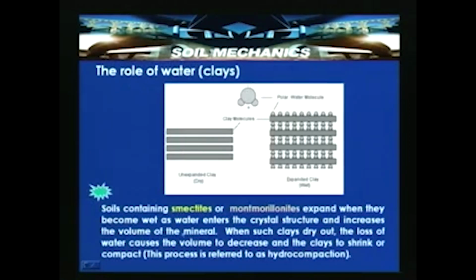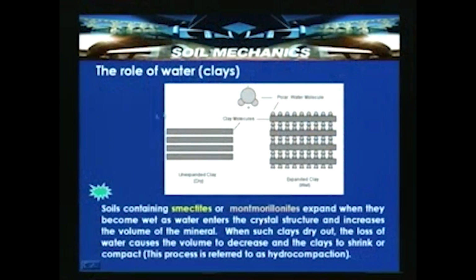Contrary to this, the behavior is entirely different when you supply water to a clay soil or a soil having smectite and montmorillonite minerals. When the water is supplied, it tries to keep it and tries to swell or expand. That particular behavior is shown in this slide, where this is an unexpanded clay and this is expanded clay with pore water molecules. So soils containing smectites or montmorillonites expand when they become wet as water enters the crystal structure and increases the volume of the material.